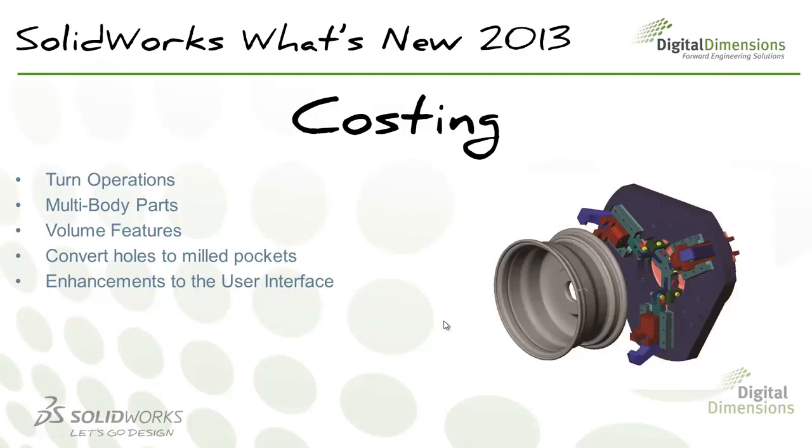Here are a few of the new features for costing in the 2013 release. One of the big ones is support for turn operations. That's the first one I'd like to get into here today. Also support for multi-body parts. And as we get into that, I'd like to point out some different things about support for multi-body parts and analyzing the cost of multi-body parts. Also, we have this new feature we call volume features. For machining costing, volume features I believe will make a lot more accurate analysis of the cost of a model. Also, we have a couple new commands, one of them being the ability to convert holes to milled pockets in costing, as well as some enhancements to the user interface that I definitely think are worth pointing out.